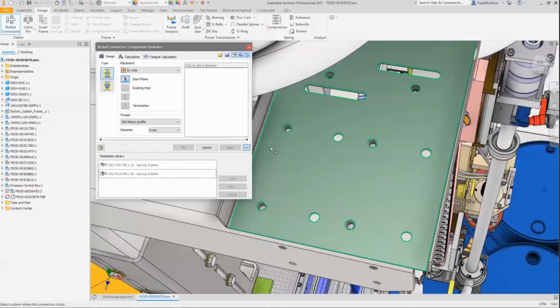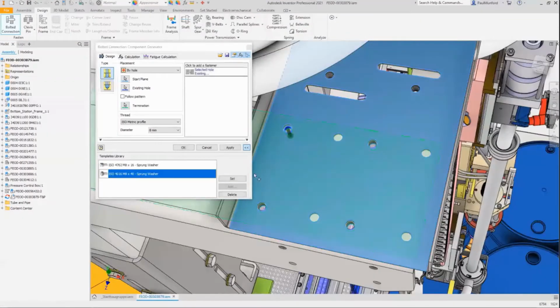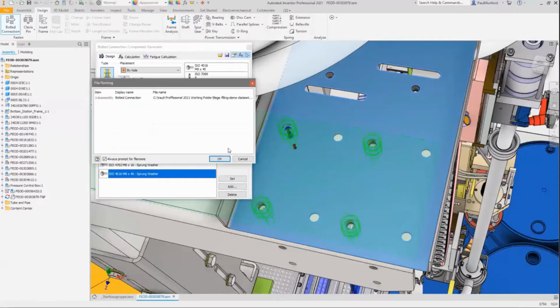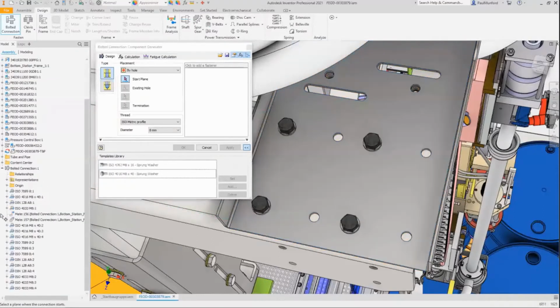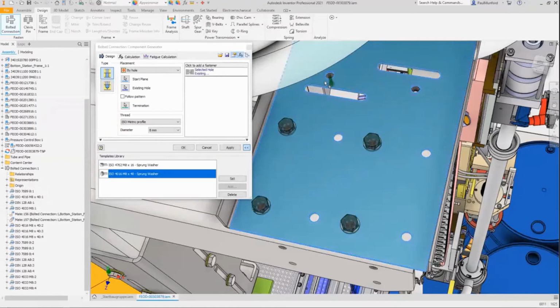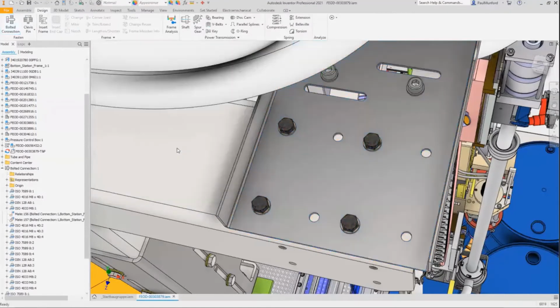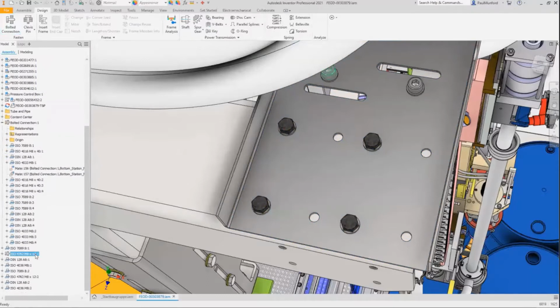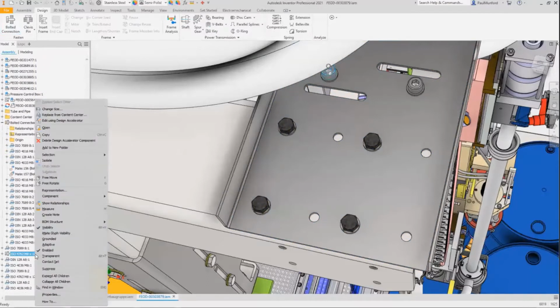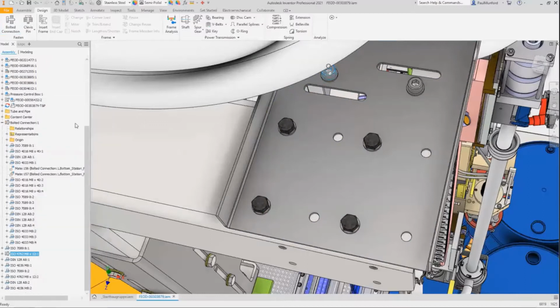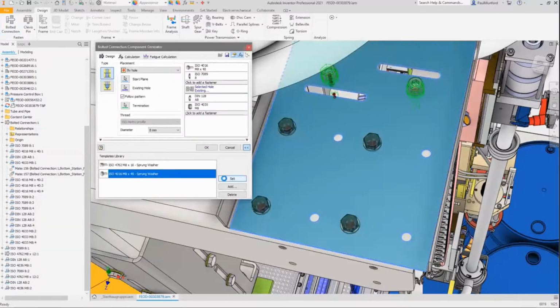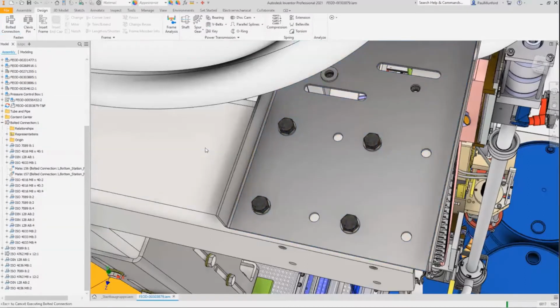So to help you structure your assembly environment, we've rolled out the functionality last seen in the shaft component generator to bolted connections. So in this example, notice the new option to disable the subassembly structure. With the option active, no folder or subassembly will be created on disk. So the individual components will be inserted directly into your assembly. So this gives you more options for structuring your assembly and organizing your data to best suit your needs.